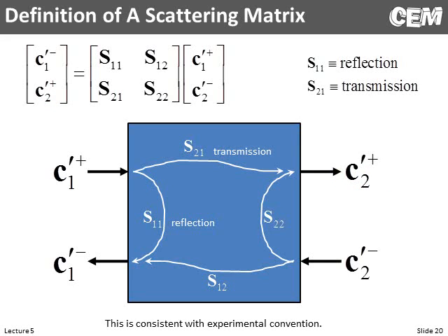So the scattering parameters have physical meaning, and this is the convention that's been used for many decades, and it is so common in electromagnetics labs. You'll hear many people just say the word S11 and not even say reflection, because it's so common. Everybody hears S11 and immediately, oh, okay, that's reflection. And the same with S21. That implies transmission. So common, people will just say S21 and not even say transmission. So that convention has been around for decades.